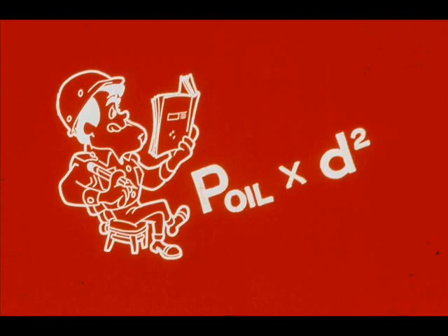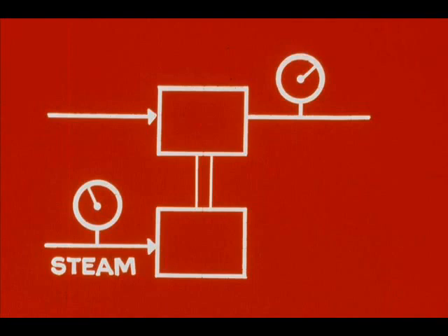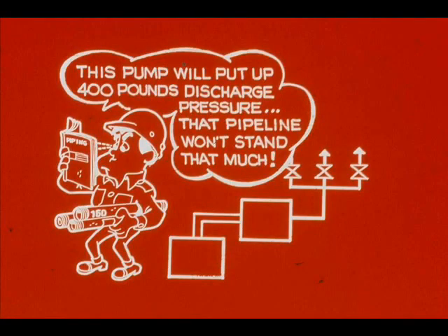Understanding the terms we have discussed will help you to make certain calculations concerning steam-driven reciprocating pumps. One of the more commonly needed calculations is discharge pressure, pressure on the oil side. We'll call it P sub O in a formula a little later. Because the discharge pressure of some steam-driven reciprocating pumps is much greater than the steam pressure driving the pumps, you may need to calculate discharge pressure to determine whether it's safe to use a particular pump in a given piping system.